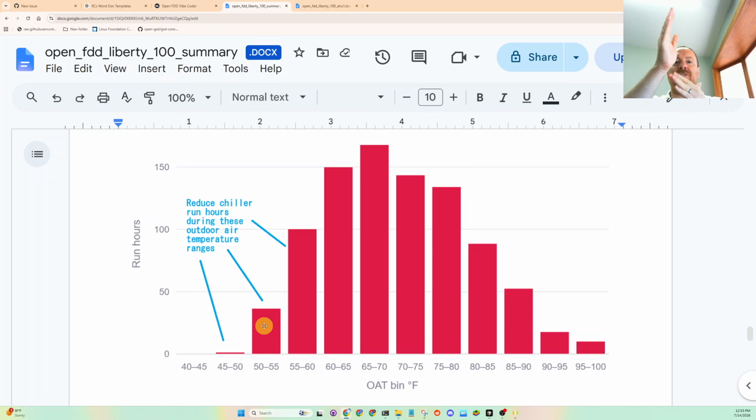There are no seals anymore. What also happens is that, even fully closed, without gaskets they can still get enough ventilation air with them fully shut because they leak so much. But it also causes a lot of problems if it's really cold, or if it's really hot, humid air, and you're ventilating the building too much.